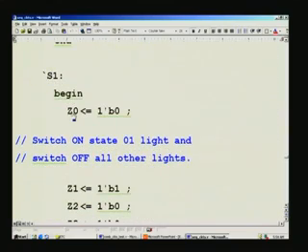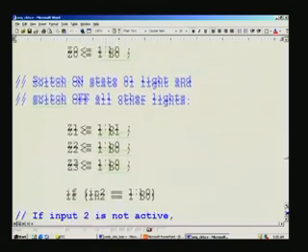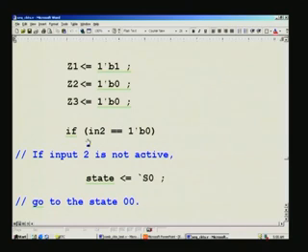And similarly, in S1 state, it all depends upon the inputs. It may come to this state only when those conditions are satisfied. Suppose it has come to this state, then you need to switch off all except for 1, that is here. And once again see into condition, and if into is 0, go to S naught state.